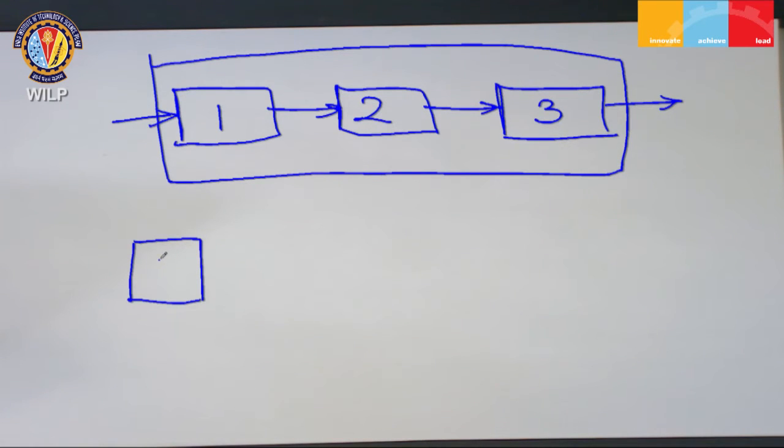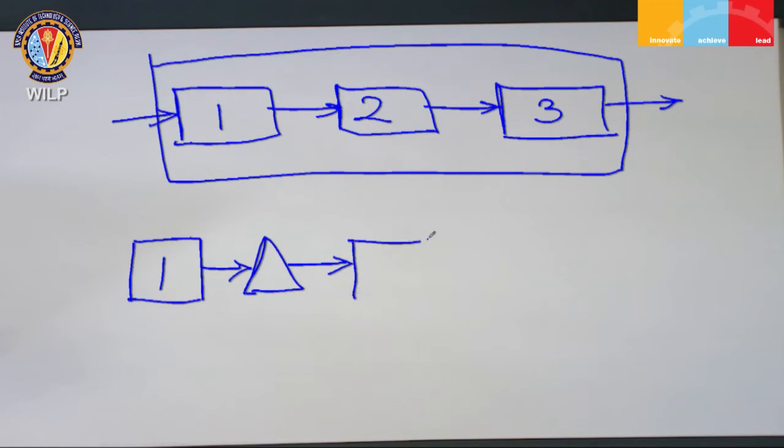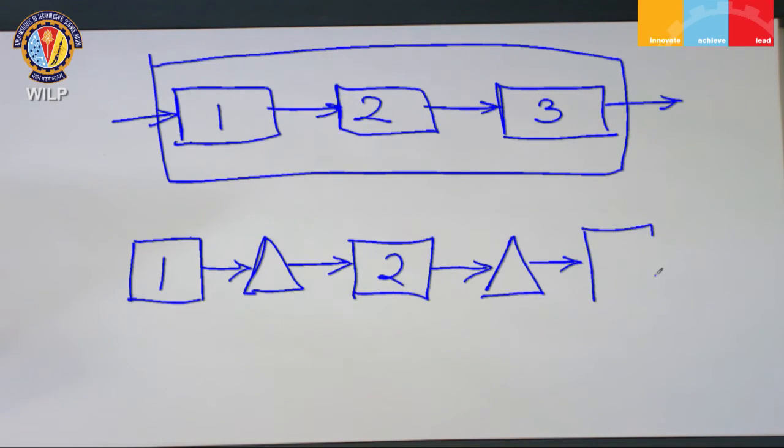if we had these processes a little disconnected, so that now you have inventory, and in value stream mapping, inventory is depicted as an upright triangle as opposed to the industrial engineering symbol, which is an inverted triangle. So if your process looks something like this, where after the product is finished on machine 1, it goes and sits in some WIP or work in process area until it is required at process 2.